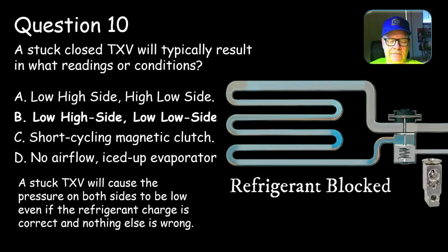One of the things that I thought was funny there, I say it was funny, her compressor eventually locked up, because when you pull the refrigerant out with the machine, you also pull out a little bit of oil. And they had done this enough to where they had depleted all the oil in the system, and her compressor seized up. And so we basically had to replace her compressor, flush the system, and all that kind of stuff. We got her going again.